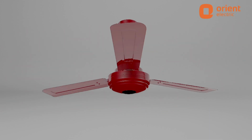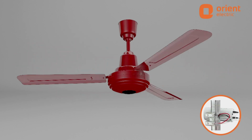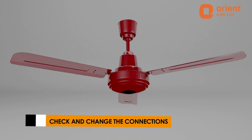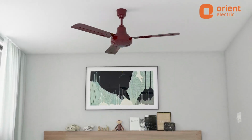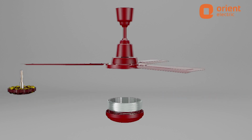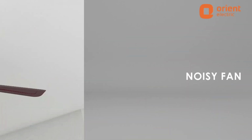Does your ceiling fan rotate in the wrong direction? If yes, then the problem could be a defective stator or wrong connections at the terminal block of fan. If the problem is due to wrong connections, check and change the connections. If still the fan rotates in reverse direction, replace the stator. Your fan will start running in the right direction.